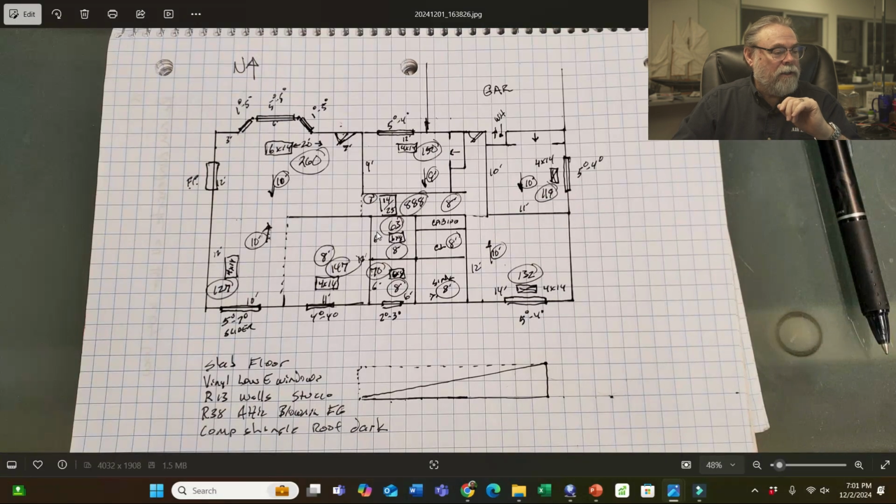What do we have on this one? Let's see. We've got 12 foot. So we have this hallway, and this hallway goes all the way down to the corner here. And we know it's 12 feet across here because this is that center line, again, where the trusses are. So this is 3 foot, again, 2 foot, and then half of it's 3 foot. So a 3-foot hallway goes down.